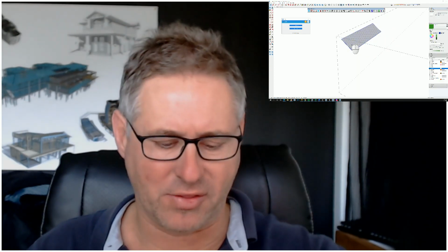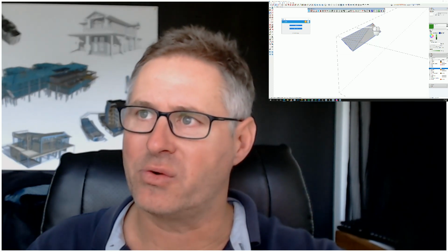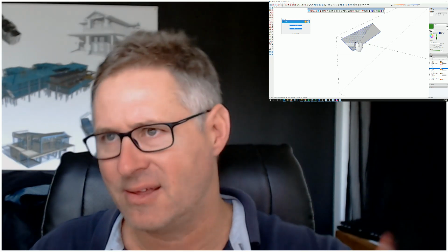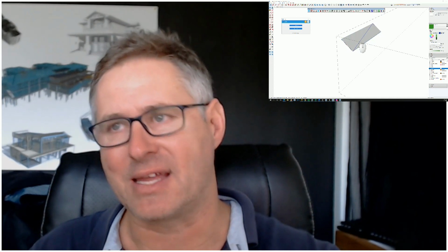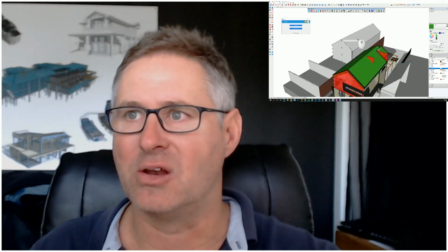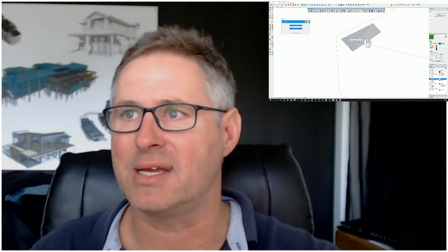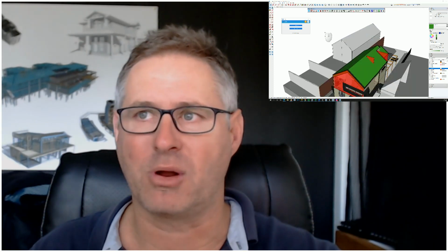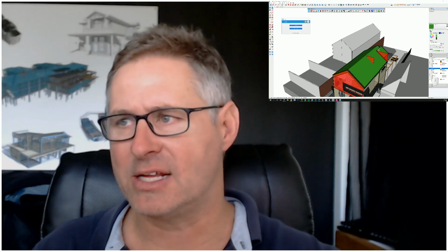And triangulation, if you're not aware of what that is, when geometry is imported by a lot of things, it actually comes with a line through here because it makes triangles, because that's the way the software works. And then they basically hide a line here, and it looks like one face, but unfortunately it's two, and that's a problem. So the optimization tool has actually solved that problem, and it's organized the model.